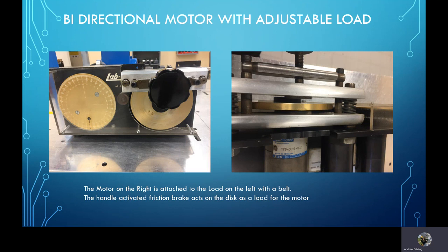So that's the idea of this lab, was just to get you familiar with the concept of what happens when you add a speed control or a flow control to a motor, and how it affects speed and how it also affects the extension and retraction of a cylinder, right? So flow control is very important for speed, and we can preset that on some systems, and in some systems we want that to be dynamic.